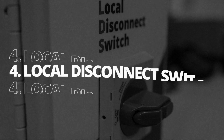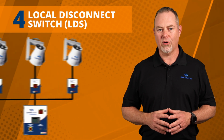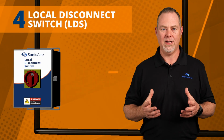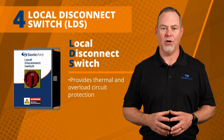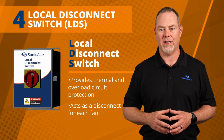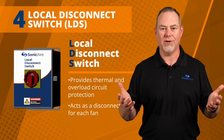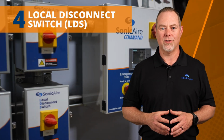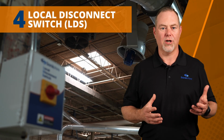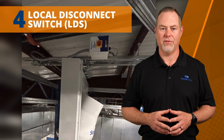Now, the local disconnect switch. This is possibly the most important electrical decision in your fan system design. Each fan requires its own manual motor starter, which we refer to as the LDS. The LDS provides thermal and overload circuit protection, as well as acts as a disconnecting means for each fan. The question at hand is, where would you like the LDS installed? They can be grouped together in one central location, generally near the command control panel, or on a wall or column near each fan, or in the ceiling immediately adjacent to the fan.